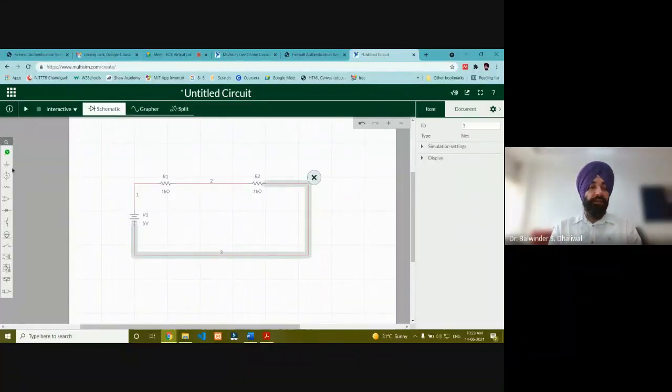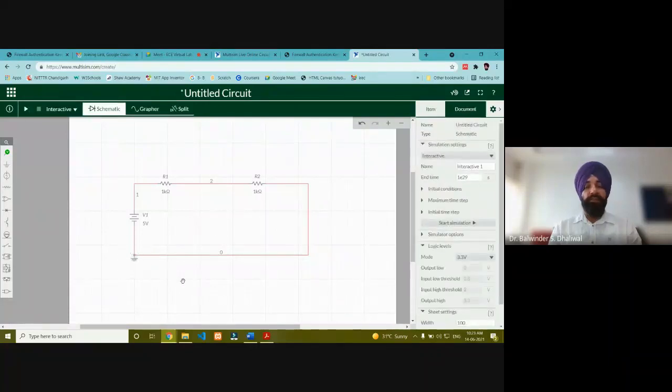So this was the circuit, and here we had this ground. When we connect a voltage probe at this point, by default this tool will measure the voltage between this point, where we connected the probe, and ground. If we do not connect the voltage reference, the reading shown here will be the voltage between this point and the ground. If we are interested in reading the voltage across this component only, then we need to connect the second terminal here, as we do in our physical lab, right?